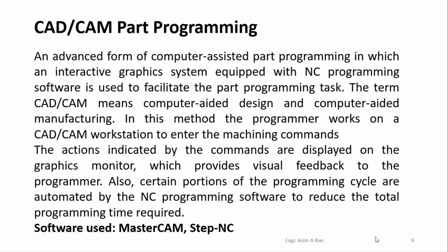CAD/CAM part programming is an advanced form of computer assisted part programming in which an interactive graphic system equipped with NC programming software is used to facilitate the part programming task. The term CAD/CAM means computer aided design and computer aided manufacturing. In this method, the programmer works on the CAD/CAM workstation to enter the machining commands.